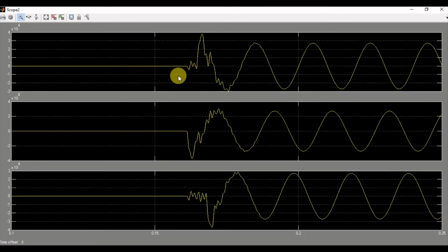As soon as the fault is recovered, the voltage appears. But there is one more thing to notice, that after the fault is recovered, the initial voltage waveform is abrupt. This is because of the presence of inrush current in the transformer.